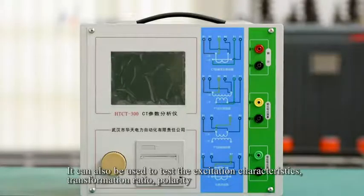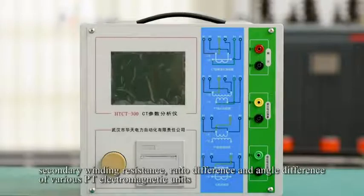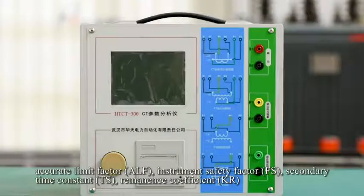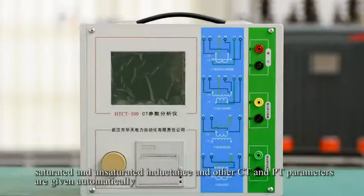It can also be used to test excitation characteristics, transformation ratio, polarity, secondary winding resistance, ratio difference, and angle difference of various PT electromagnetic units. The parameters of CT and PT, such as inflection point, voltage, and current, 10% or 5% error curve, accuracy limit factor, instrument safety factor, secondary time constant, length coefficient, saturated and unsaturated inductance, and other CT and PT parameters are